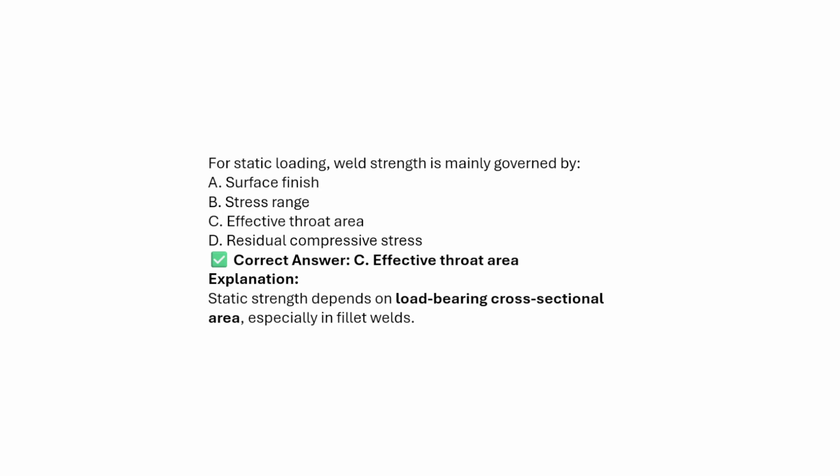For static loading, weld strength is mainly governed by: surface finish, stress range, effective throat area, residual compressive stresses. The answer will be effective throat area. The static strength depends on the load bearing cross section area, especially in fillet welds.